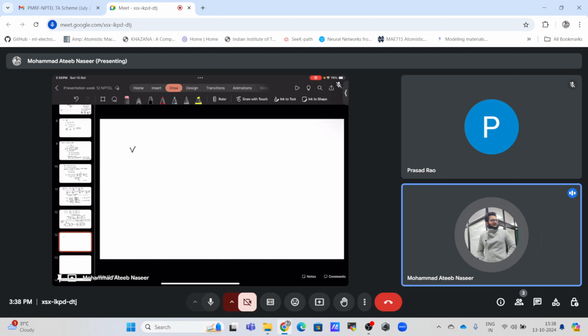So the resistance will become a conductance, which is represented by GS, and the current source will be represented by Vs times GS. It will be simply this thing, and this GS will come in parallel with the Y11. This will be simply our I1, this will be Y11, and this will be Y12, which is controlled by V2. This is our V1, and this is not associated with this thing.